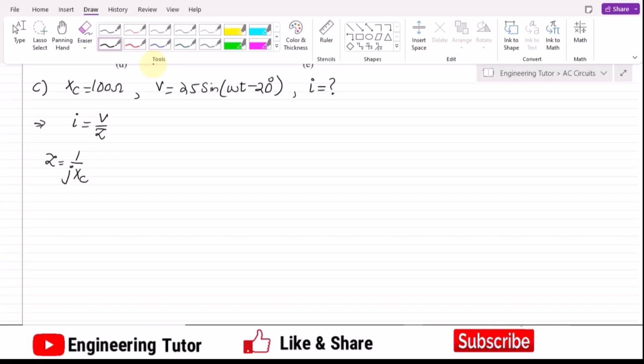So here it would be minus j over X of C, because I can write that j multiplied by j is equal to minus 1, and therefore 1 over j is equal to minus j.